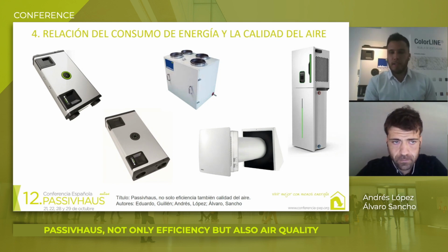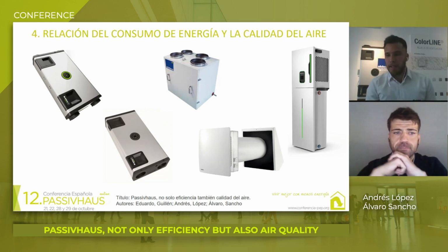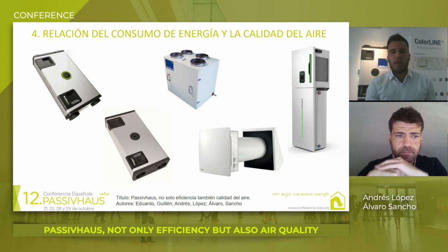Thank you, Alvaro. When addressing indoor air quality in homes with low energy consumption, design is essential together with the implementation of innovative systems to guarantee continuous flow and also air purification and heat recovery, as required in the Passivhaus standard. For the preparation of this article, we use the technical information for the advanced ventilation and purification system designed by Aldes, specifically the Inspire Air Home model, as you can see in the picture, which consists of ventilators with electronic switching equipment, low consumption, a parallel panel heat recovery system, and also a compartment for air filtering.